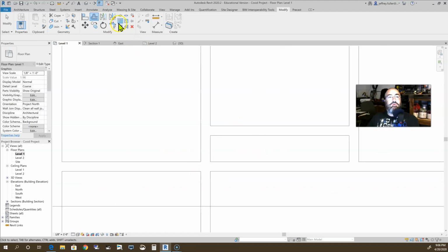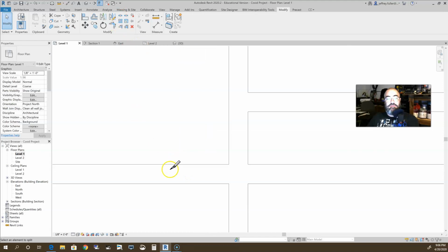And of course, you got to see how I use the split element tool. But to show you a little bit more about the split element tool, when you're splitting things, always make sure you look at the direction of that dark line that you see kind of moving along with the knife. Sometimes you might be in an intersection like this and you're wanting to split between these two walls, but it actually lines up horizontally. So keep an eye on that when you do it. Sometimes it's just a very little movement that would cause it to split in that direction.